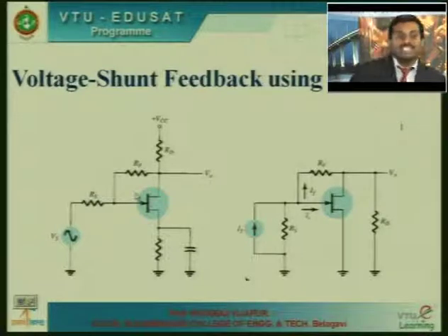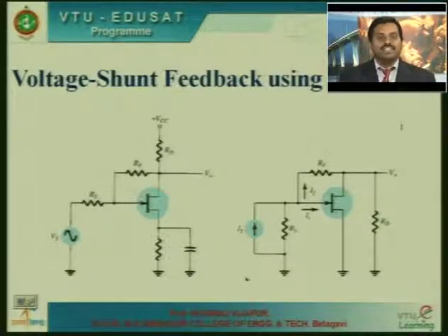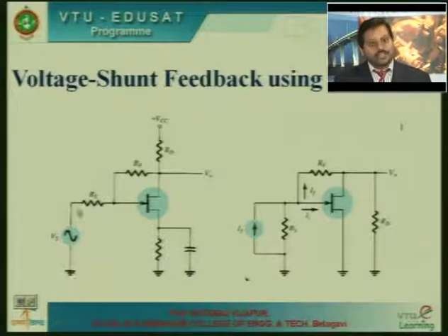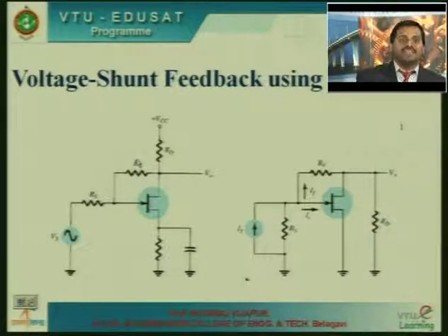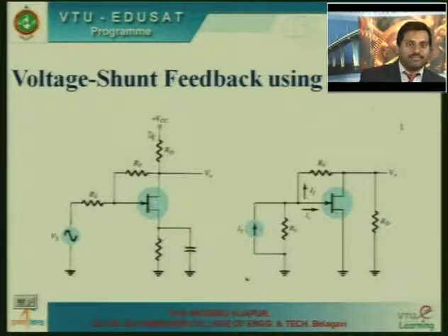What does the circuit arrangement consist of? It consists of an input voltage source Vs, and a resistance Rs, which is the resistance of the source. RF is very important here. RF is a feedback resistor connected between the input and output. Then you have a supply source VCC and a drain resistance RD.